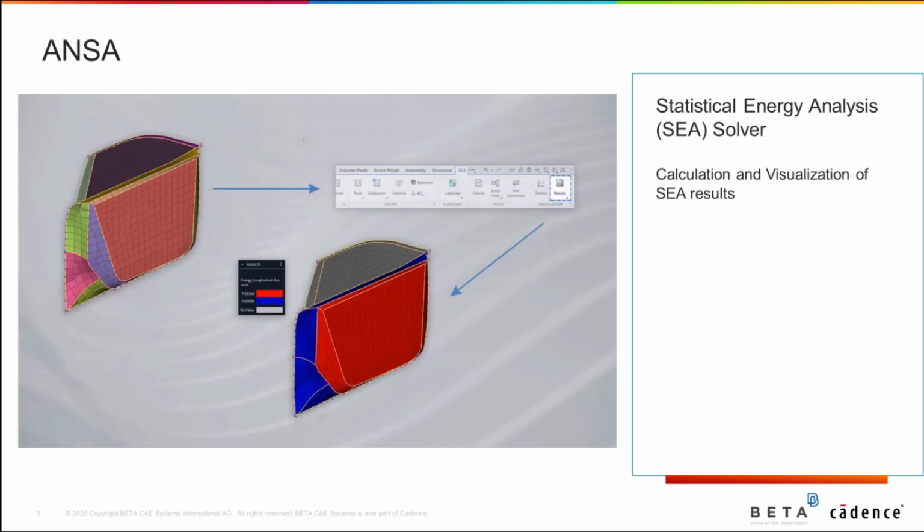Key metrics such as energy, velocity, pressure, modal density, modes and band, modal overlap, and wave number can now be computed directly within ANSA, eliminating the need for external solvers. Results are integrated within ANSA and can be saved for future reference or to be reloaded if necessary.